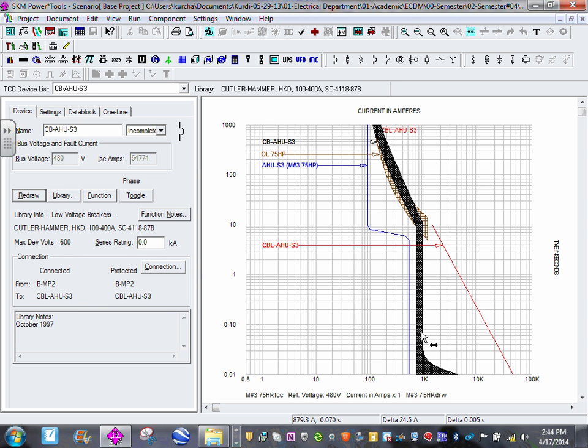The reason we do that is that we can then not oversize the circuit breaker, which means we can lower the available arc flash energy, because your instantaneous is down and you're not allowing it to go too high, and you have a lower PPE and all this good stuff. So if you're doing design, especially if you're an engineer, always ask on chillers and rooftop units and all this stuff for at least an adjustable breaker, if they're using circuit breakers. If you're using fuses, always ask for a dual element time delay fuse, because 175 is easier than 300 in terms of arc flash energy.